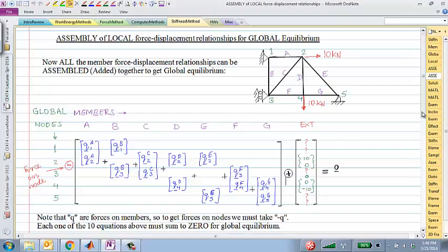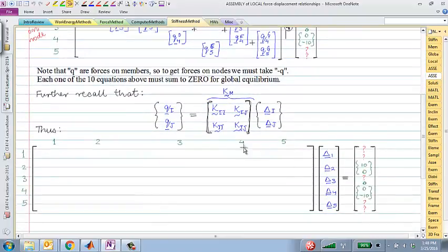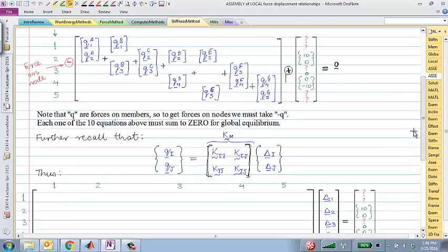But before we do that, as I mentioned, we are going to try to fill out this matrix because we want to convert these element forces into something that involves element displacements. So let's see how we do that. Anybody recognize this equation? Where is this coming from? What is this equation? Qi, Qj is equal to Kii, Kij, and so on, and delta i, delta j.